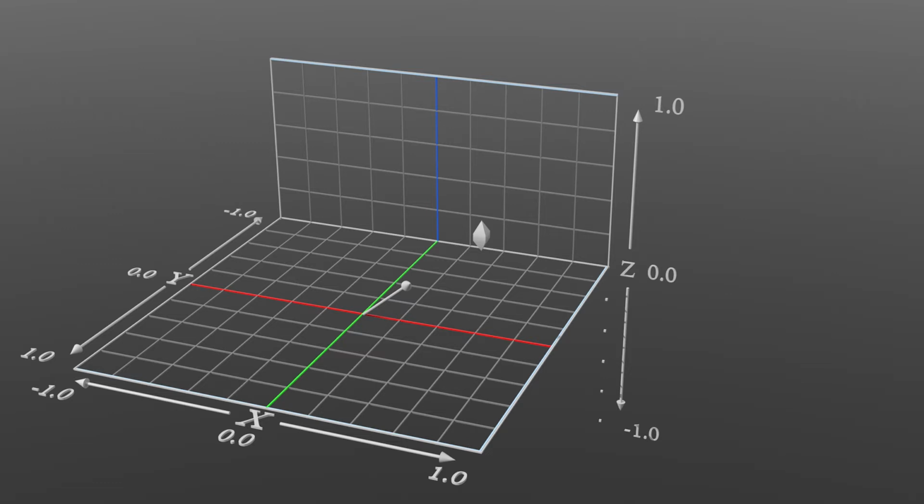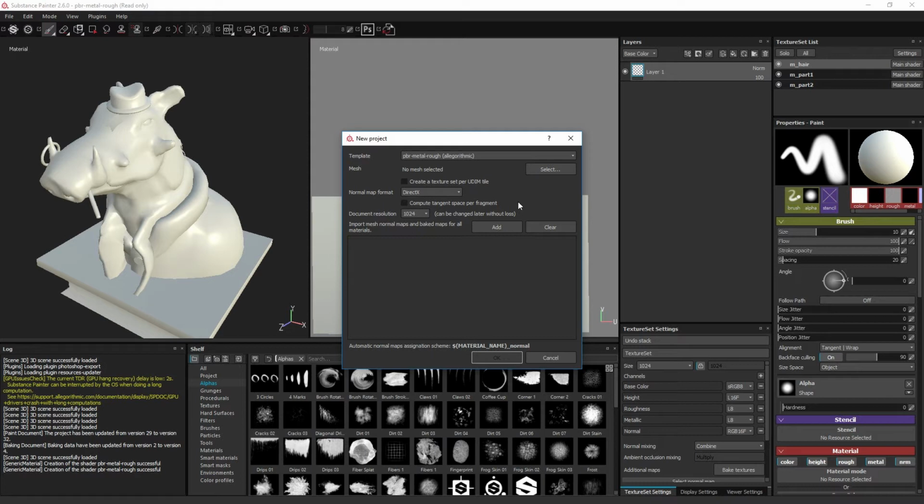The two techniques result in vastly different normal maps because the normal map is baked to conform with the vertex normal. In other words, related to the x, y, and finally the z component. If the modeling environment sets the vector through three defined components, but the texturing environment reads only two of the components, it changes the vertex normal of the object within the texturing environment from what it originally was before.